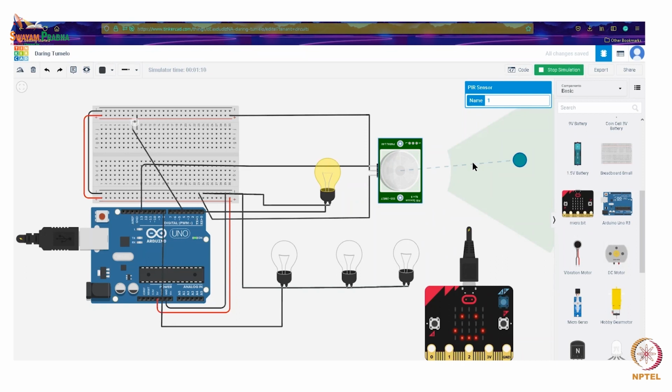And this module basically looks for the temperature changes, and it observes the ambient temperature. Now, if we got the presence from the PIR module in the server, and the temperature is above a certain threshold, then we are sending the data through something called the BACnet protocol. So we have the Daikin air conditioning system. They provide you with something called a BACnet system. The BACnet systems can be communicated with similar to what we are seeing here, and that's how the whole thing is running. Once we have both conditions, the temperature being above the threshold and the presence being detected, then we are actuating the BACnet, and then the ACs are getting turned off. So that's the whole actual implementation of the system that we have.